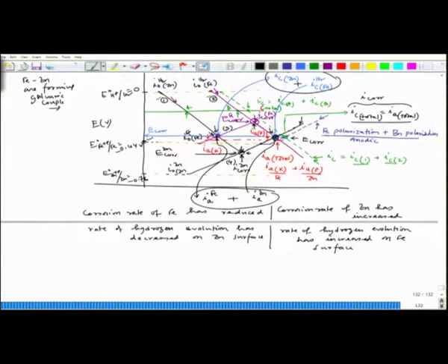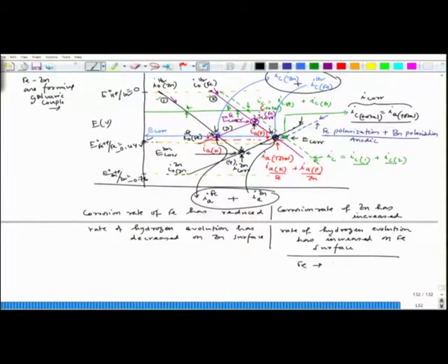So, as we have understood before, if we have a preferable cathodic reaction on a surface, that surface becomes cathode, and if we have a preferably anodic reaction on some surface, that surface becomes anode. So, here iron turns out to be the cathode area, since preferably hydrogen evolution takes place on that, and iron dissolution or the anodic reaction for iron has decreased to a great extent.